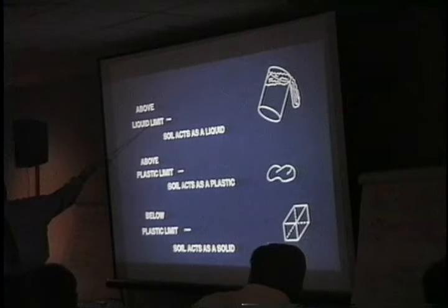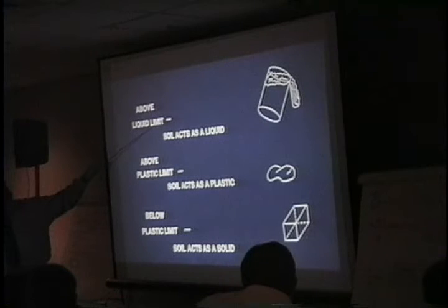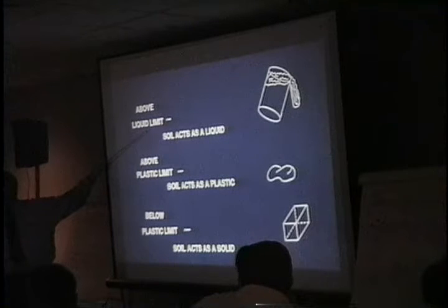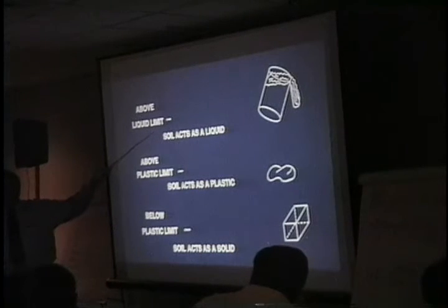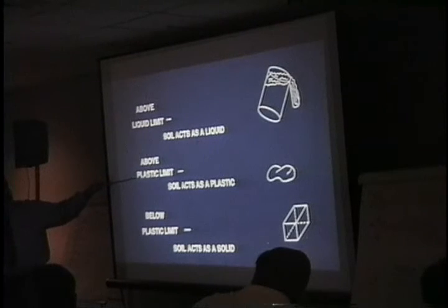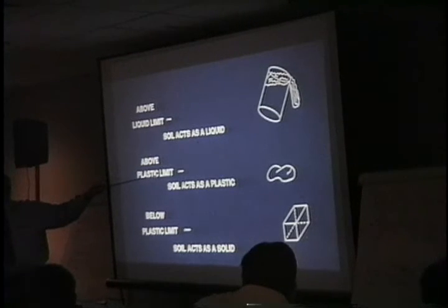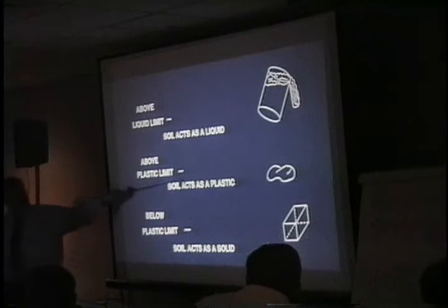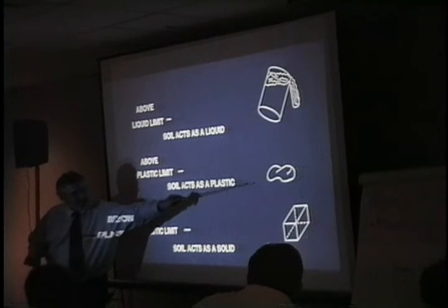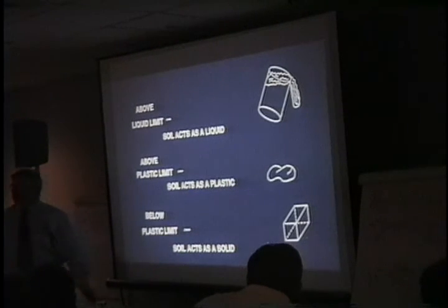The liquid limit is the maximum amount of water a soil can hold before it turns liquid. So it's the limit of water before it liquefies. The plastic limit is the limit of moisture while it's still plastic, but before it becomes solid.